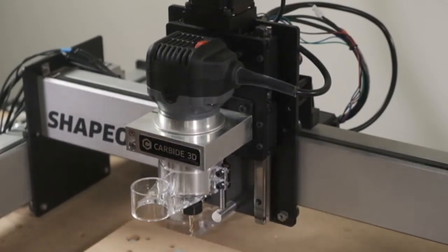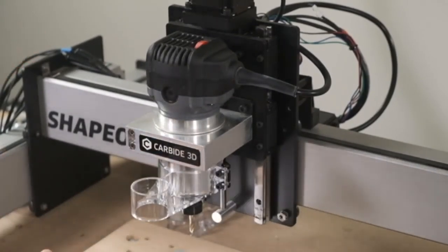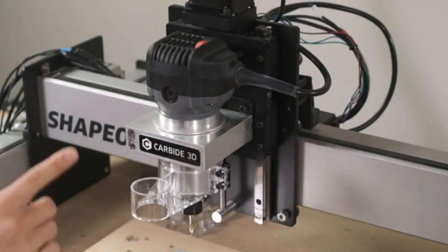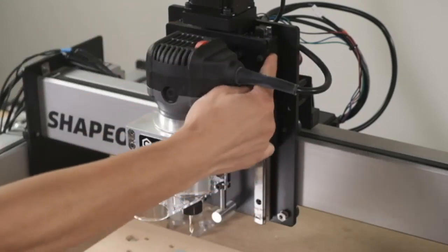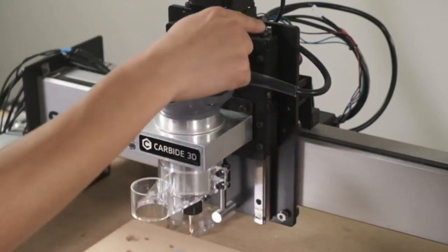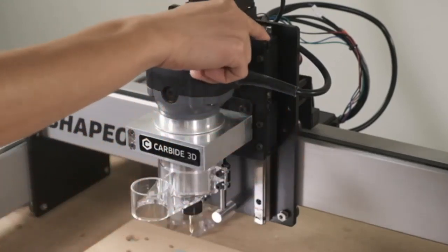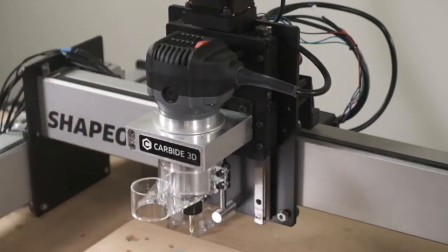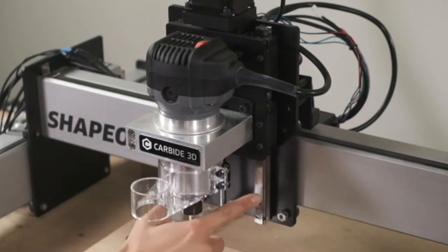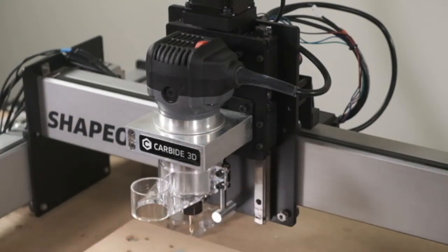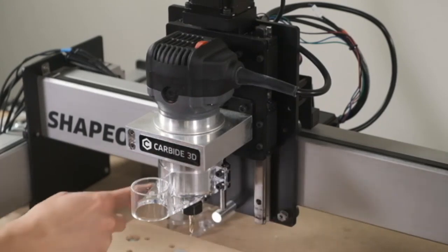So here you have a Z Plus, and I am blocking the studio lights. These are linear rails with bearing blocks, and these are generally packed full of a light grease that provide lubrication. So as they travel over the rails, the silver parts, they'll deposit a little bit of oil, and that will help keep things lubricated, keep things moving smoothly, and also help prevent corrosion.